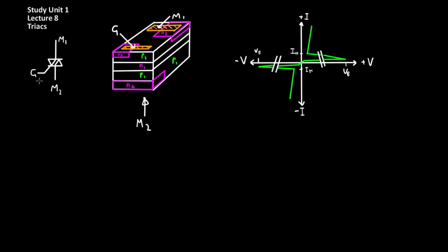The primary advantage of the triac, despite its complex structure, is that effectively 2 silicon controlled rectifiers can be implemented which share 2 terminals and only 1 gate. A disadvantage of triacs is that their complex structure normally leads to a non-optimal layout in silicon.